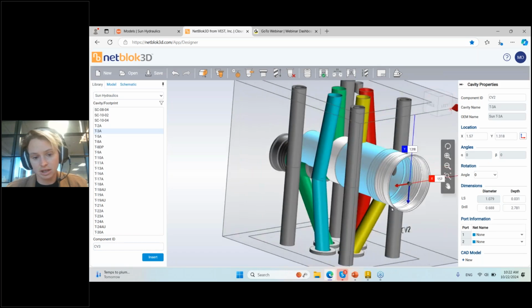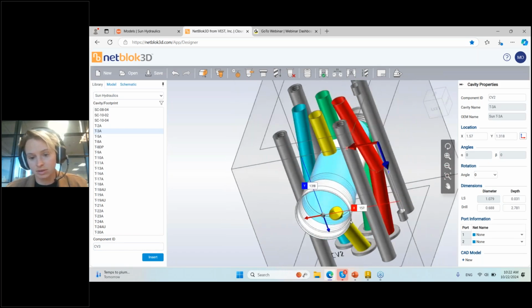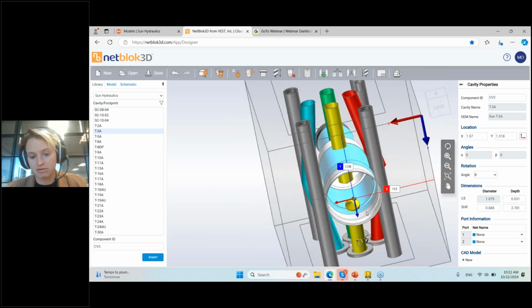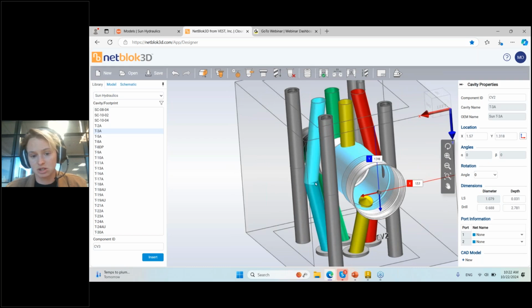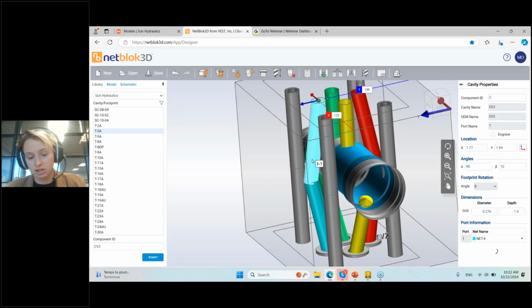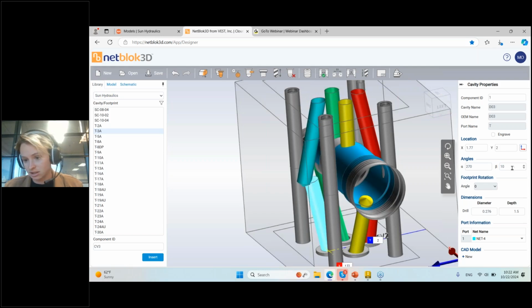And looking at it, now I can see, whoa, I've barely got room for it in my frog legs as I have them sitting now with this tank and this pressure line. So I can pretty easily adjust those if I'd like. I could have also adjusted them around the smaller cavity to make them a little tighter, a little bit less angled. But if I want to adjust the angle, I can just go here and say, this time around, let's do it 15. Let's do it 15 there.